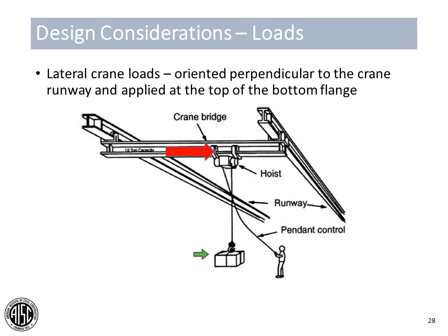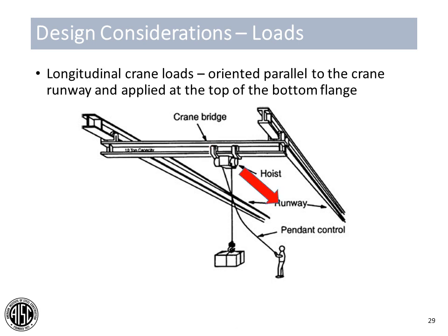It could be a skewed load being picked by the operator, or it could be due to the runway members themselves being slightly skewed, or the end trucks on the bridge crane assembly itself being slightly skewed and causing an accidental lateral force on this runway member. That's where we'll discuss the CMAA installation tolerances. They're very critical to ensure we're not imposing unanticipated loads on our runway system.